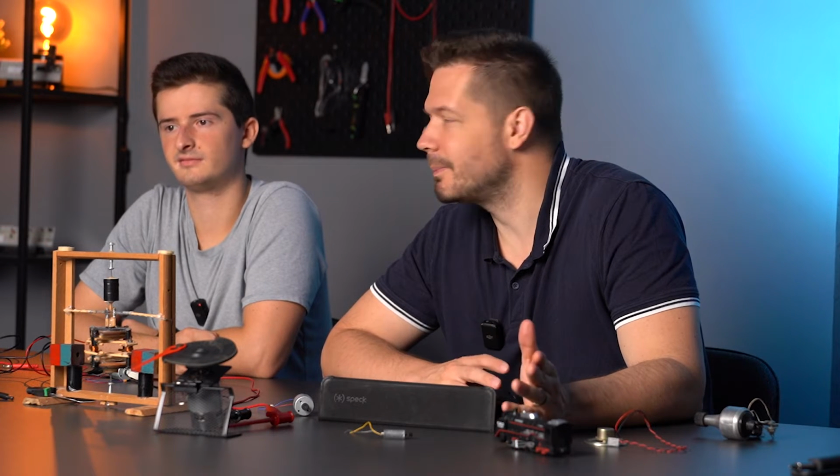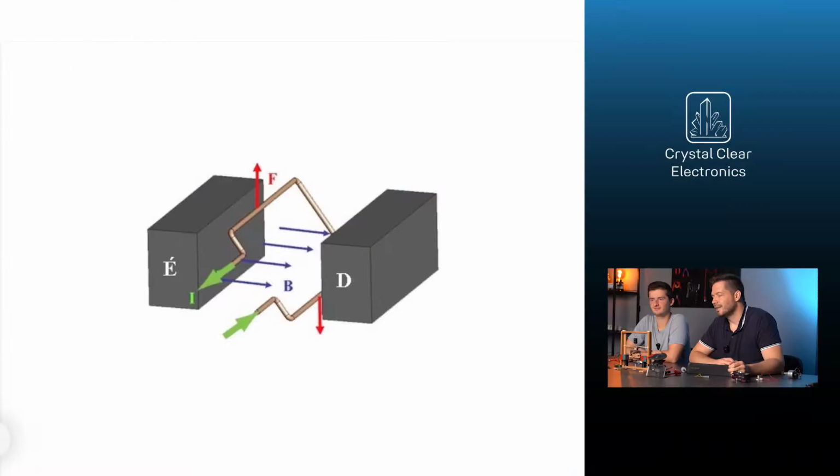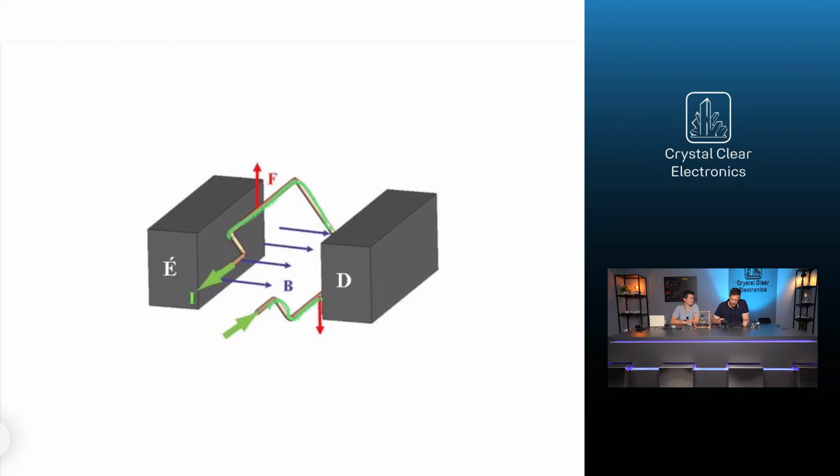Inside the DC motor, which is the simplest structure we're examining right now, there is a stationary magnetic field created by permanent magnets. We can also use the term permanent magnet abbreviated, which is PM. Imagine what happens if a loop with a current flowing through it is placed inside the magnetic field, as shown in the figure. Lorentz forces act on a section of the conductor and create torque, causing the loop to rotate.